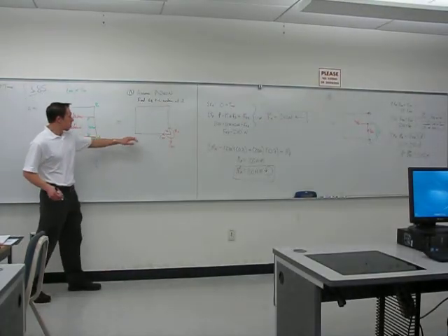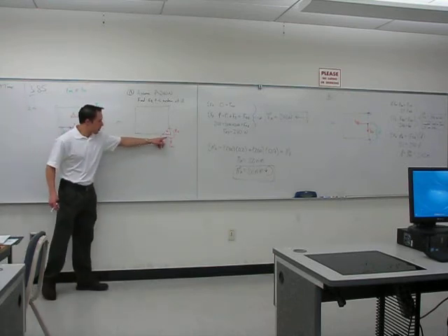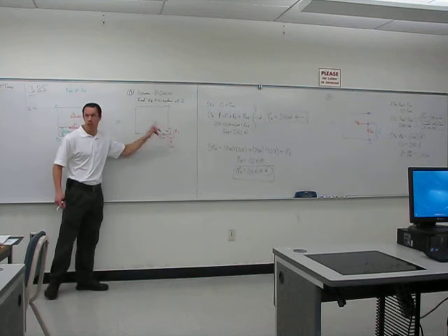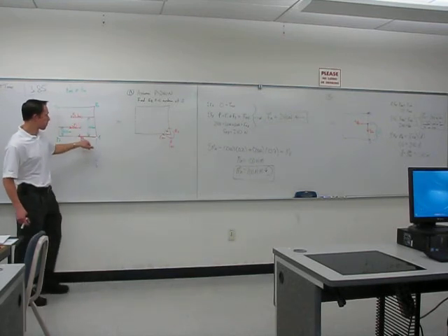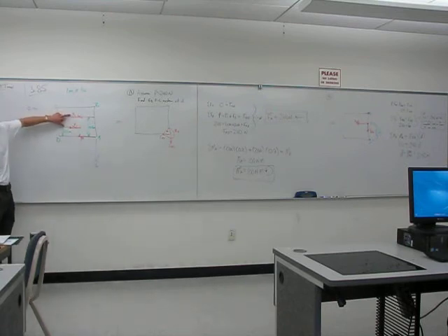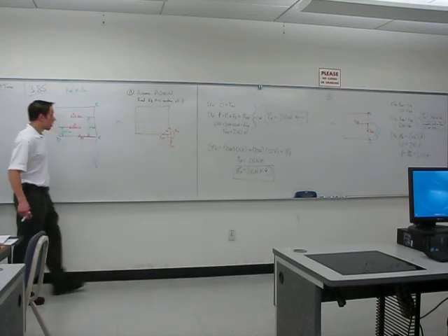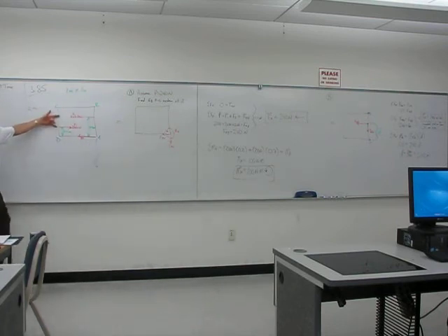So what happened? We have 3 forces from this picture, and in this picture, remember this moment represents a force couple. So here's essentially what happened. The force P stayed at the point A. Notice that F1 and F2 actually make up a force couple. The moment of that couple is what ended up here. Notice the distance between those 2 forces is 0.5.